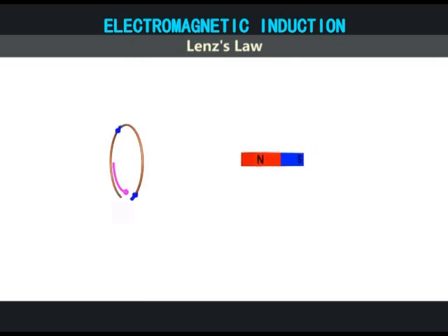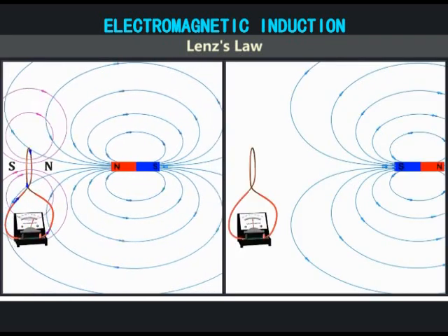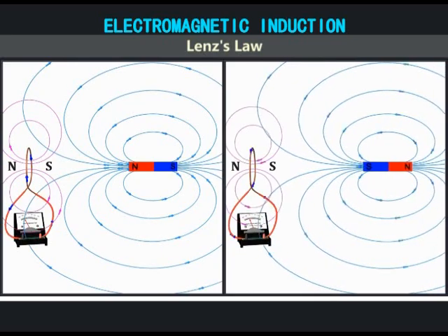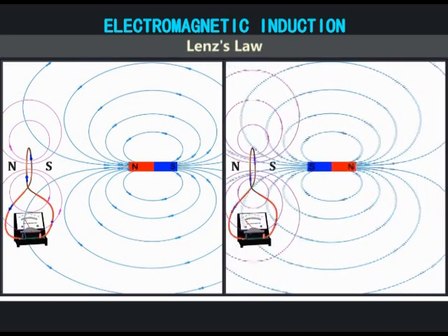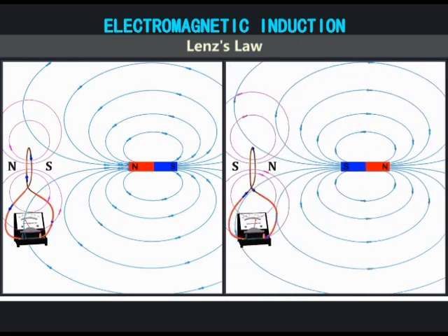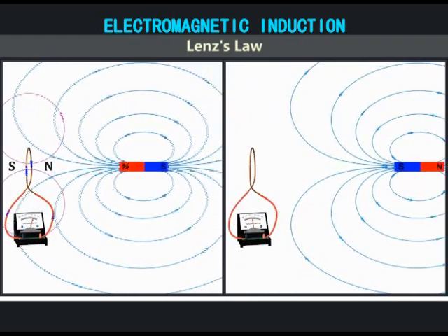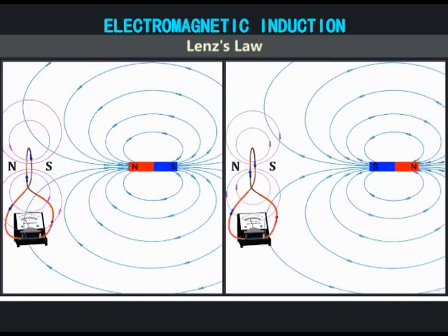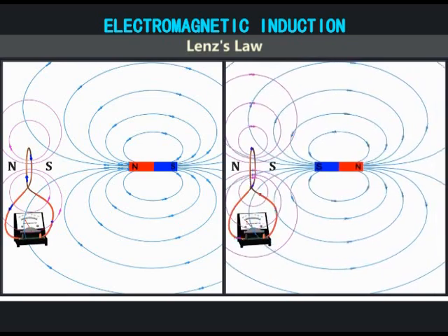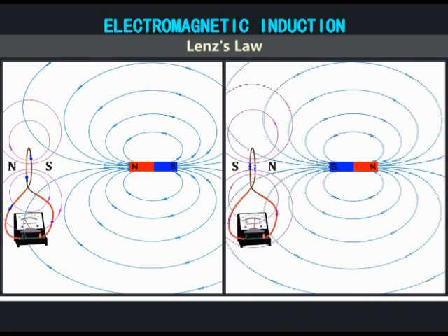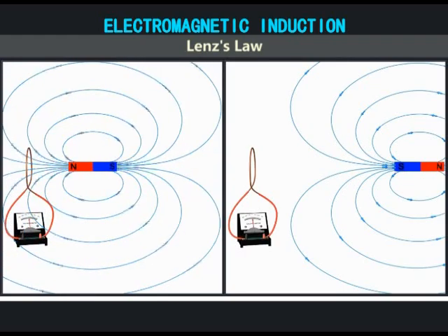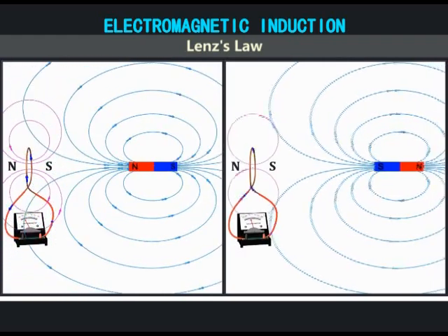So if we induce current in a conductor, at that very instant when the current flows, that conductor also creates a magnetic field around itself. And so at that instant, we shall have 2 magnetic fields, one from our bar magnet and the other from the conductor. That makes sense now, right? Good. The interaction of these 2 magnetic fields is the basis of Lenz's law.